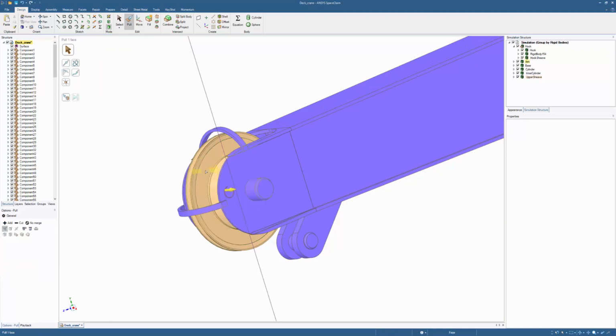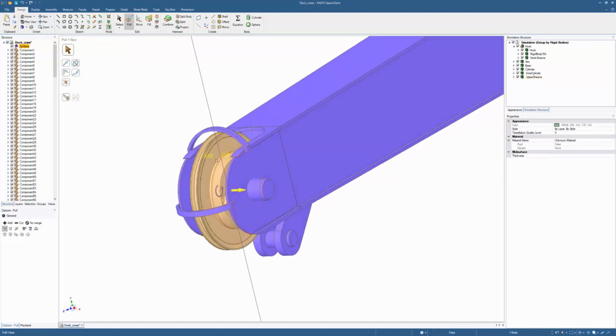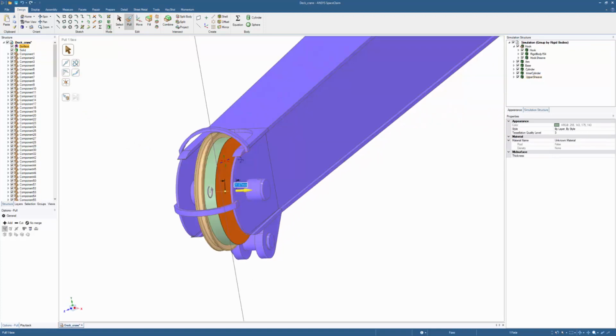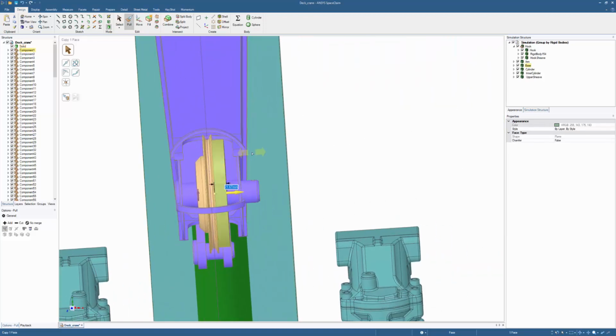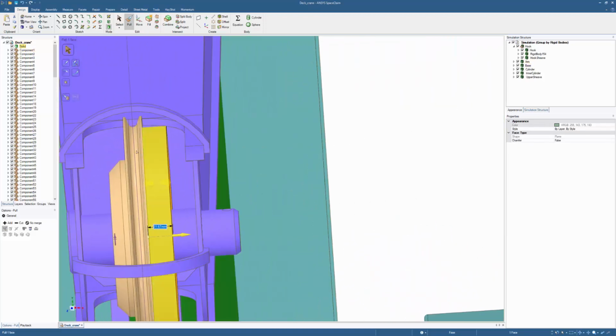And then we use the pull tool to extrude this circle into a solid cylinder. And it should have the same width as the original triangle mesh. So we will move this primitive so that it's aligned with the original triangle mesh.